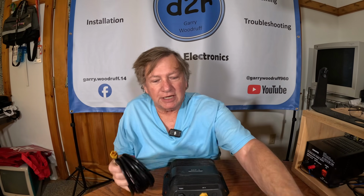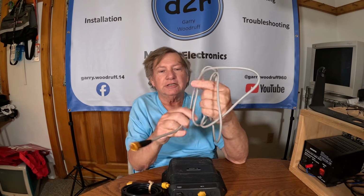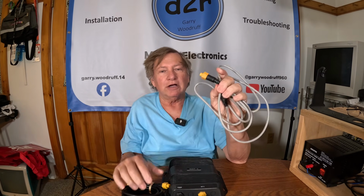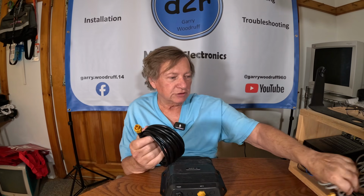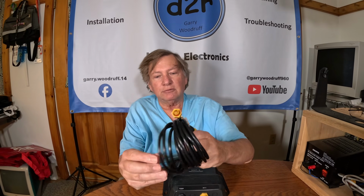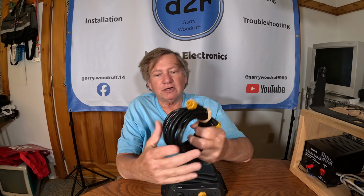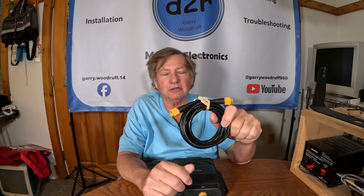There are 2 different types of Ethernet cables. This is an older Ethernet cable. This is where they use a little bit different wire type, and I had a lot of these fail. This is the old gray one. So if you have those in your boat, if you start having issues, just replace the cable with the black cable. I've had a couple guys try to use aftermarket cables. I just stick strictly with the Lowrance ones.